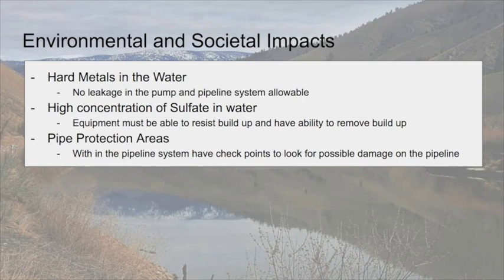In addition, the high concentration of sulfate in the water is difficult on our equipment, and it must be able to resist buildup and also have the ability to remove buildup when it does occur. There were also some pipe protection areas implemented within the pipeline system, and these are checkpoints to look for possible damage in the pipeline and assess the life of the pipeline.